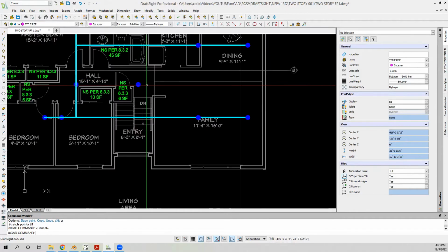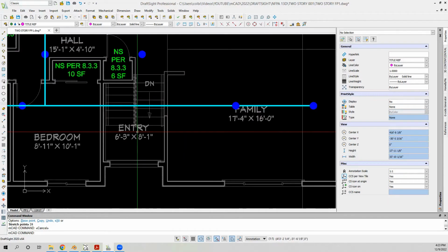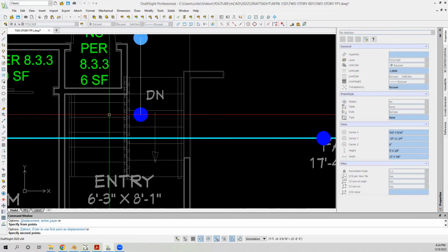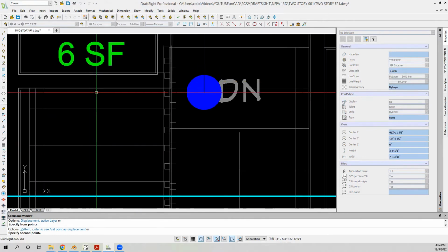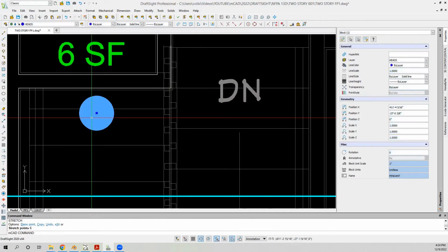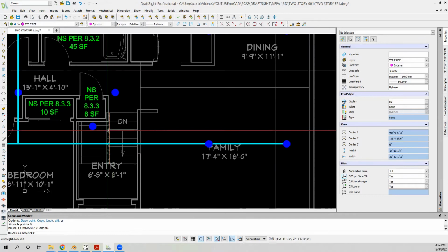I don't think there's any way to do this without 3 heads in this entry hallway area. It's pretty funky. Let's see. Also got to figure out how to do it so the heads don't interfere with each other. They can't be closer than 8 feet to each other if they're in direct path to one another. So we got wall in between here, so that's fine.